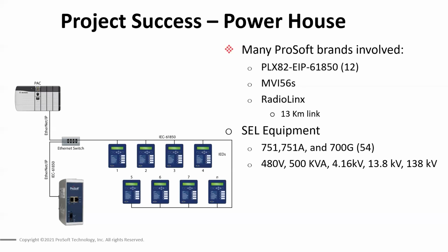And then the next question: without Goose Publisher, you cannot send control commands to the relay? Without Goose Publisher, you can send MMS control messages to the relay. They're just much slower than the Goose Publisher messages. So if you're designing load shedding applications and the like, MMS control messages may not be fast enough, but Goose Publisher certainly is.